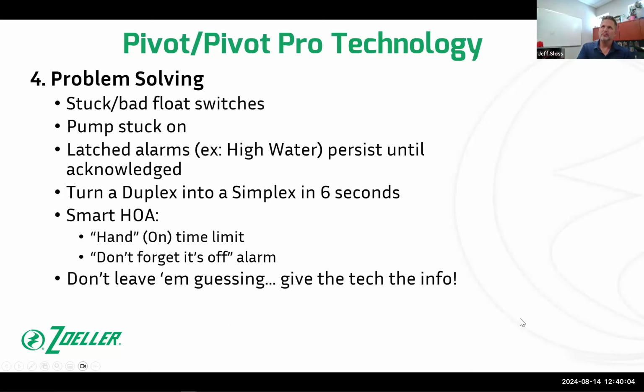All right, so just a couple problem-solving things. We talked about stuck and bad float switches. We're going to try to overcome that. Pump is stuck on. How did we overcome that? How did we solve that problem? We have a continuous run timer.